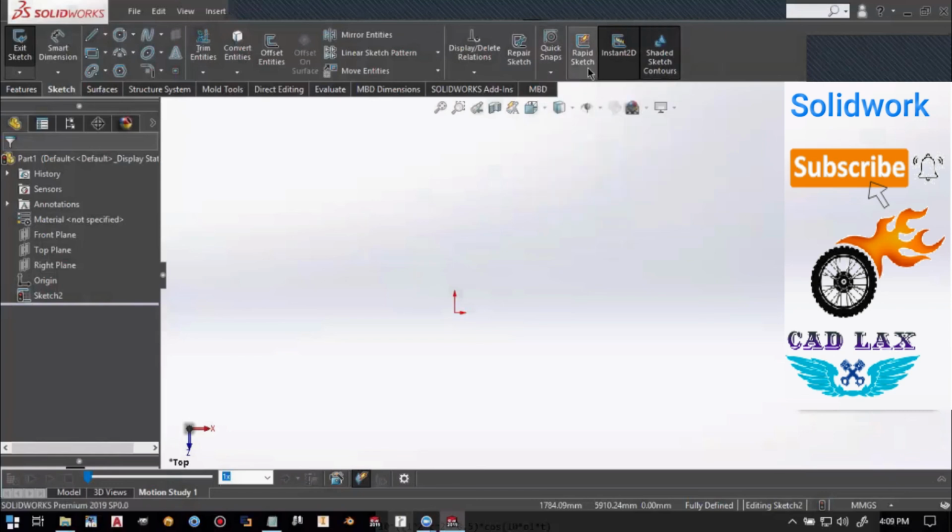Rapid sketch. This tool is useful when you create a sketch directly on 3D objects. If I have created any 3D object, you can directly sketch on the faces of it. This is also, you can say, the dynamic UCS of AutoCAD. Instant 2D. If you want to change the 2D sketch without going into the edit sketch module, you can do it by using instant 2D. I'll also explain it later.